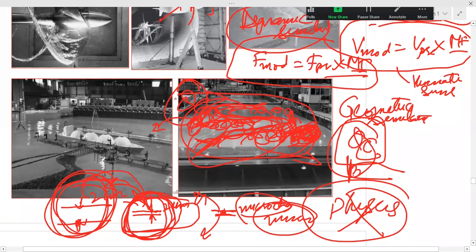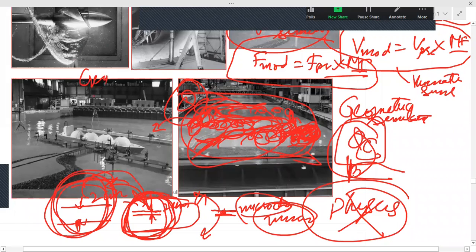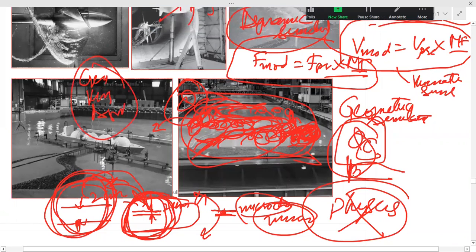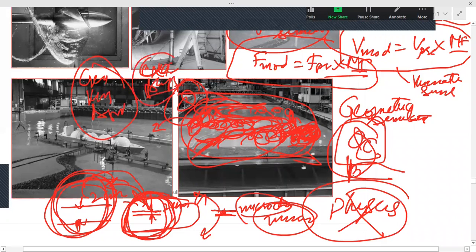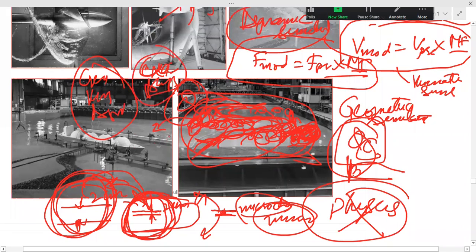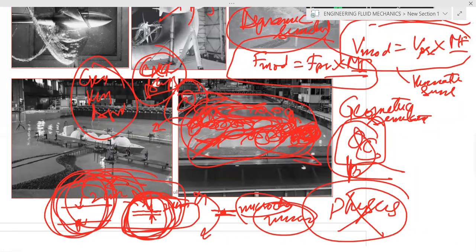So in terms of geometric, then kinematic and then dynamic similarity, you should also maintain the fact that exact or accurate physics is captured. If physics is not captured, there is no need or no worth of this analysis. And that factor you were pointing out, that also actually involves a lot of experience and a lot of study after you have identified certain non-dimensional numbers, that which factor is correct and which factor is incorrect.